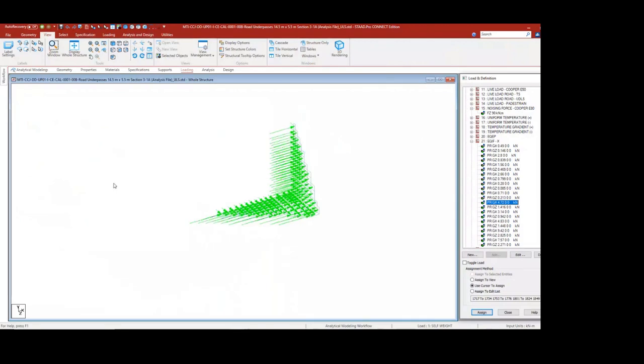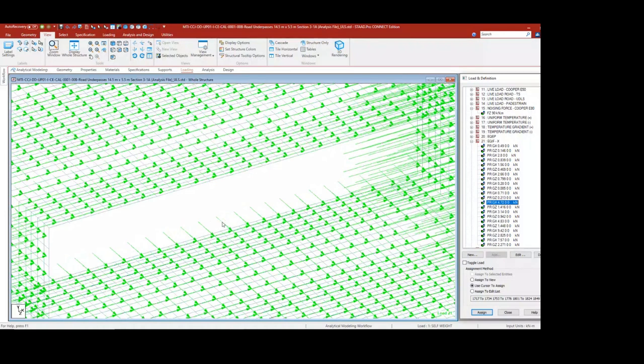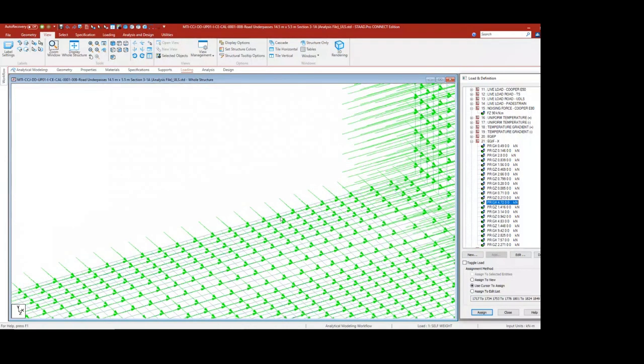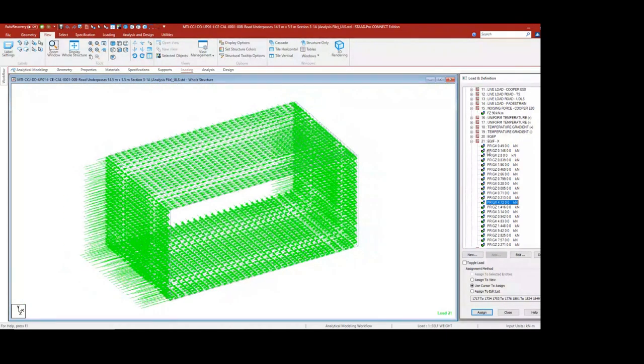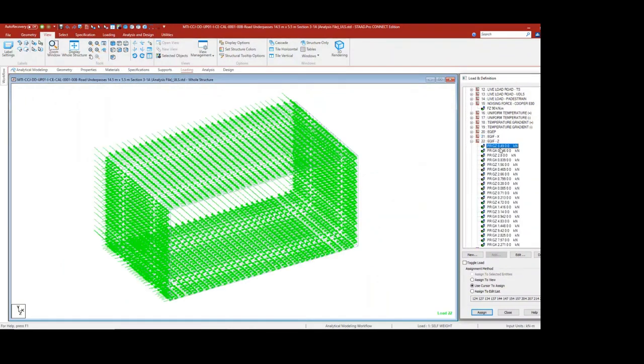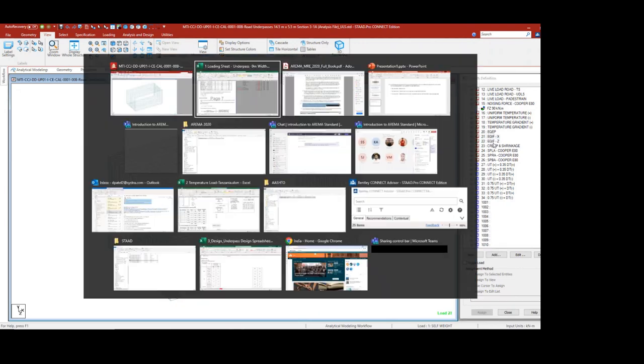This is 100% in x, if you see here, 100% in x and 30% in y. The application of this earthquake force varies from designer to designer. It's up to you; you can apply it as a nodal load also. Similarly in the z direction, we have considered 100% in z and 30% in y. It is also possible to multiply this in the combination itself, but we have applied it like this. Now, seismic earth pressure.